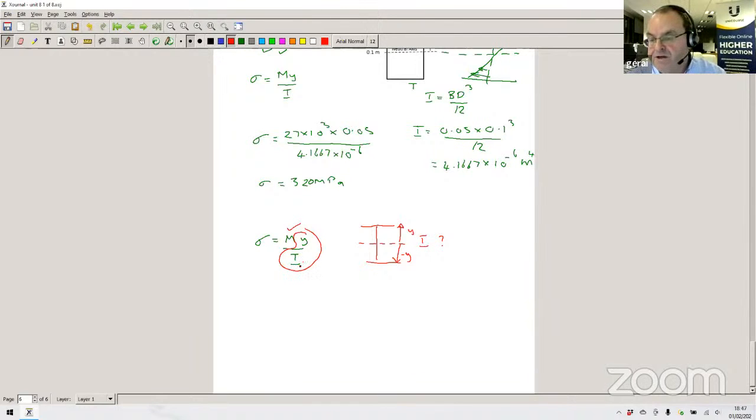And that's the second task in activity 2. So it's to find an alternative beam. Now, you won't do it first time. You'll have to try a couple of different size beams until you get a value of y over I that is similar to the original rectangular beam. And then that's your justification for the replacement beam. So replace the rectangular with an alternative I section beam.